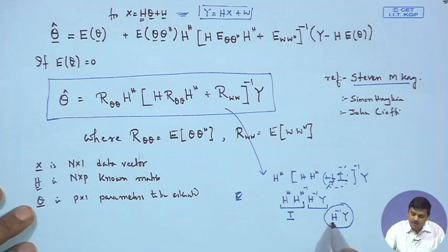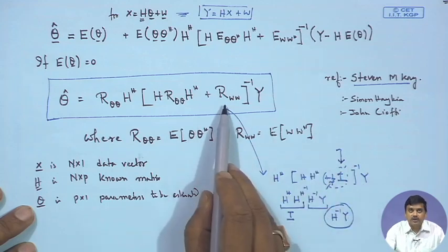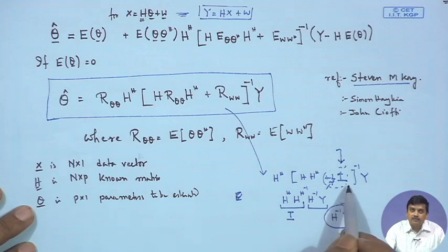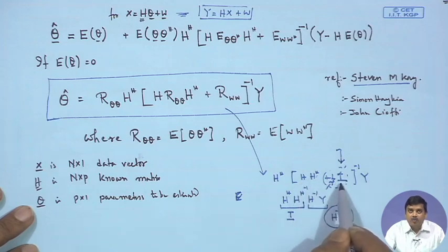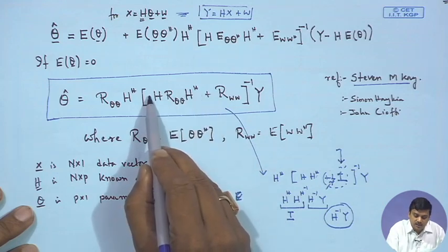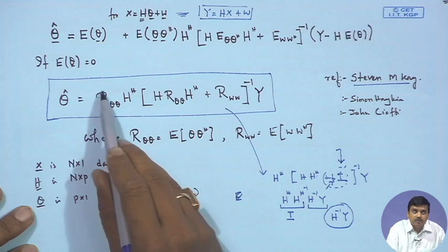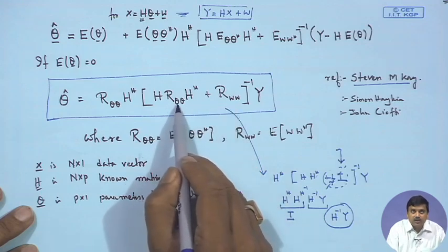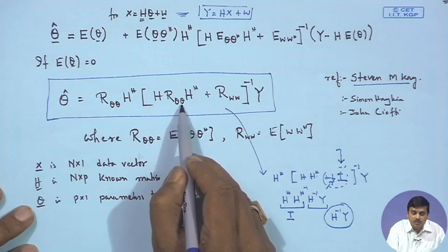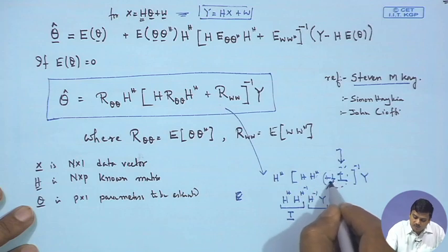The difference from a zero forcing receiver is that it introduces this particular matrix, which is the covariance matrix of noise. So, if we focus on the inside of the inversion, we will find that there is some H inverse available, but it is restricted by 1 upon SNR, because there is the noise variance, and there is R theta theta which controls the power of the signal. If I take R theta theta out, I am going to get R theta theta inverse over here, which would effectively cancel out with R theta theta, and here we are going to have R theta theta in the denominator. If R theta theta is an identity matrix with some coefficient signal power, that is the variance of theta, we are going to have variance of noise upon variance of signal and an identity matrix. So, we are going to have 1 upon gamma and I.